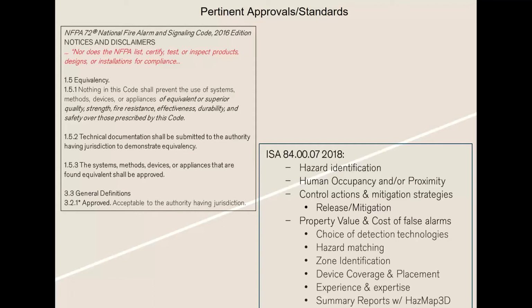And there is no such thing, right? NFPA 72 basically tells what types of equipment might be used in certain situations. So what do you do if this type of alarm happens versus that type of alarm? There's nothing in the standard that says you shall use detector XYZ and put it in this location.